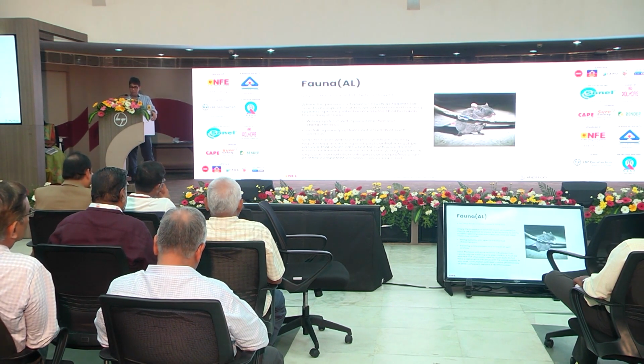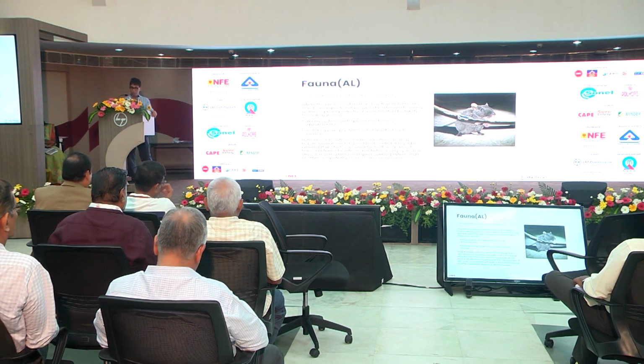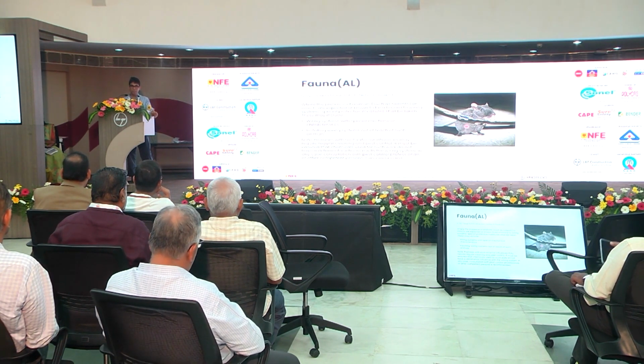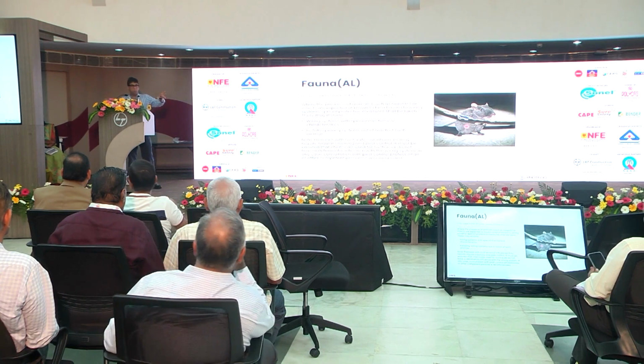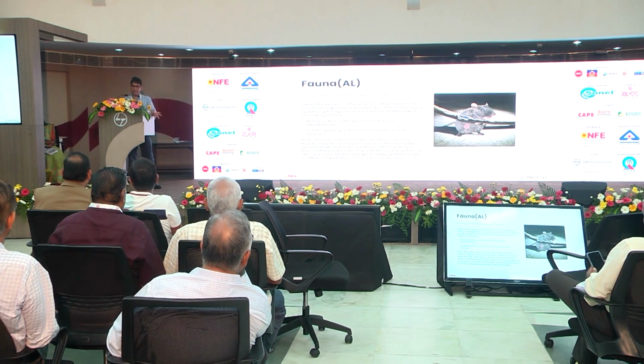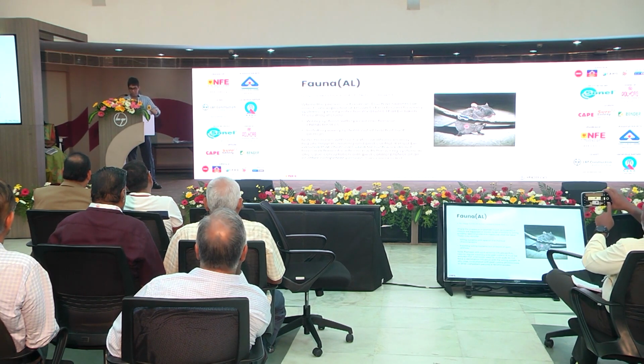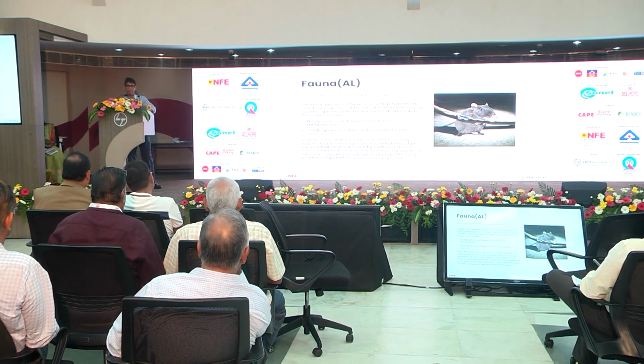Fauna, so you know, rodents coming and eating up wires. Actually last year in about August, I had a guy in Alibag who said that I keep losing power to some of my outdoor lights, and he had a spa outside his bungalow because rats keep chewing up my cables. So then I spoke to a conduit manufacturer, and they said why don't you use flexible steel conduit coated in polyamide. That way the rats cannot possibly go through the steel. Or you simply install them out of reach of such animals.